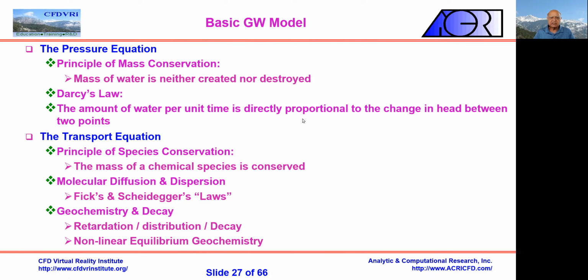It basically says that it's the difference in pressure that drives the flow. Now remember that split between the rotational and irrotational part of the velocity. In the ground, basically there is no rotational velocity. The friction is so high in these small pores that there is only the irrotational part left, which is dependent on the pressure.